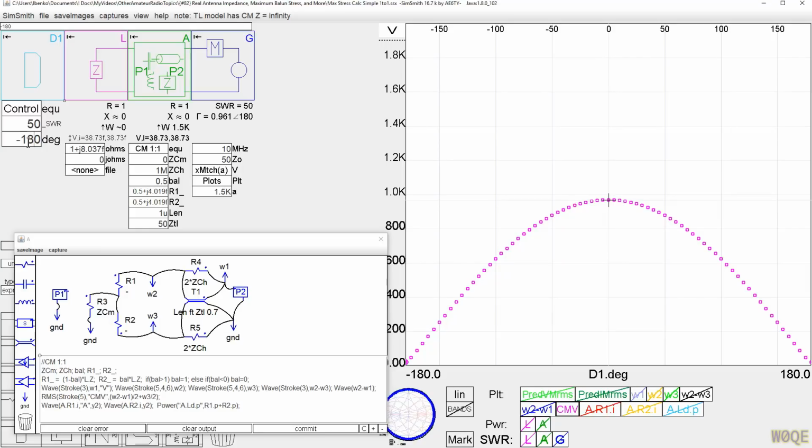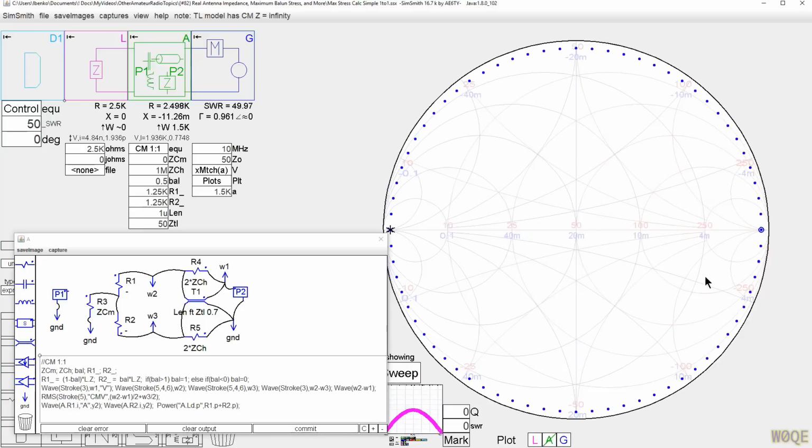So for the moment, what I've shown is we have high voltage across the balun here. The voltage we have across the balun is half of what the differential voltage is. The differential voltage determines insulation requirements and stuff in the wire, but it doesn't put any stress on the balun. The common mode voltage here puts stress on the balun and causes heating.